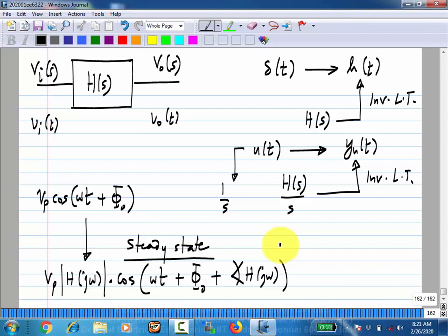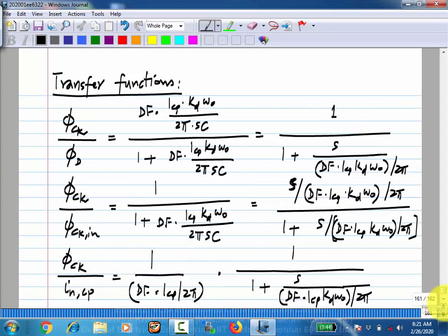Okay. So now this is fine. This kind of makes sense when you have voltage inputs and voltage outputs, right? Step response corresponds to you turn on the input to some DC value and you see what the output is. Similarly, sinusoidal steady state is you connect a sinusoid and then see what the output sinusoid is after some time. Okay. Now what do these things mean? Impulse response and step response and sinusoidal steady state response when you have transfer functions involving phases. What is an impulse here or a step?